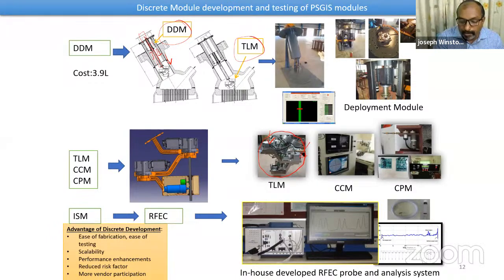So these are very high precision motors, particularly harmonic gearboxes present in the motor. Along with the motor itself, the gearbox and encoders are all integrated into a simple compact system. These give you a backlash error of only 15 arc seconds. That means normal gearboxes will have an error of a few minutes, which will cause a lot of positioning errors in robotic systems. So we go for these ultra high precision motors to precisely orient to the tubes. That is the most important part of it.